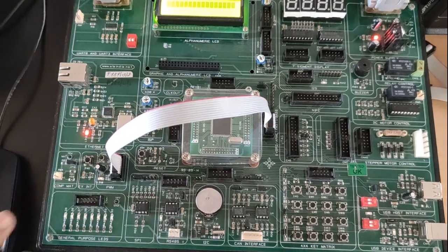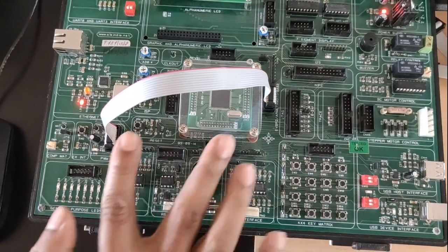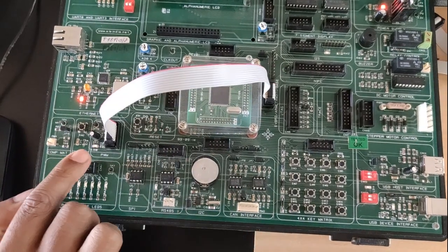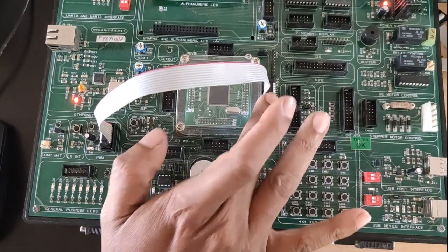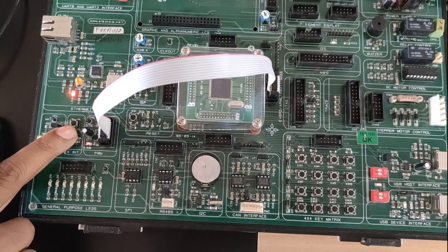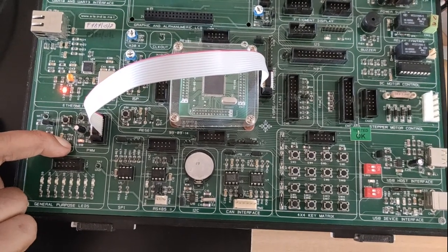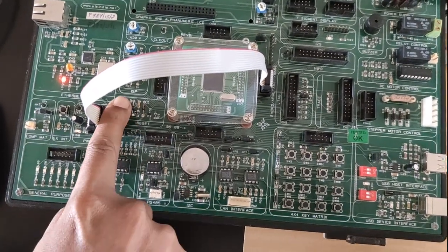Now you can observe this connection, the FRC, which is connected from CNB to CNB1. Since the external interrupt belongs to port 2, which is connected to the CNB connector B, for that reason this FRC is connected from CNB1 to CNB. Now you can observe that switch 2 is the external interrupt. We have LD10, which is configured to toggle here. Now I will reset the hardware.